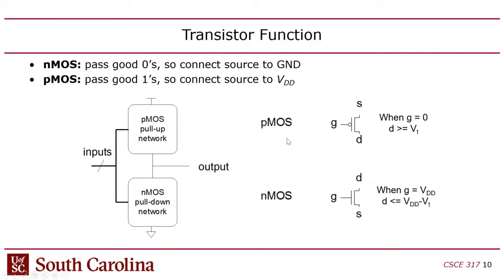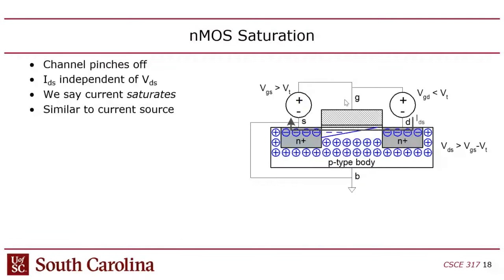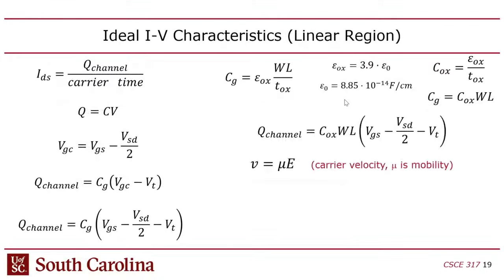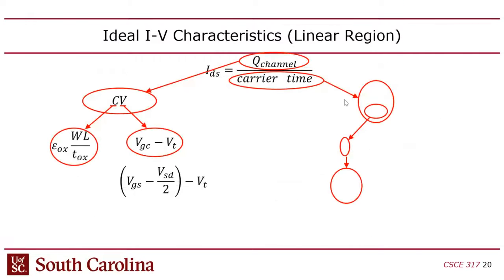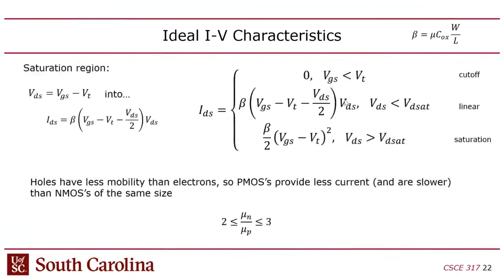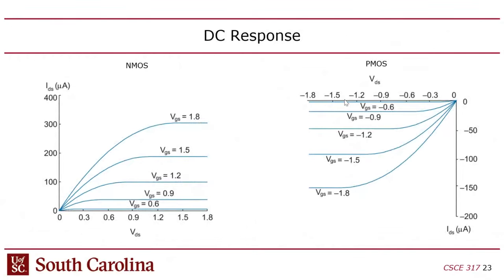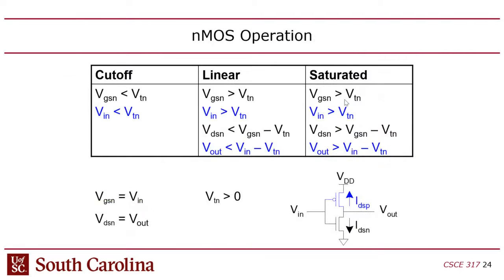The current is actually flowing from the power supply down, from source to drain, but if we express it in terms of drain to source, we have a negative number. That's why you're seeing that weird negative plot. It's just because of the convention in terms of what you label the source and the drain.